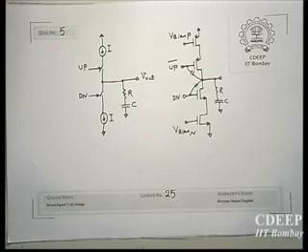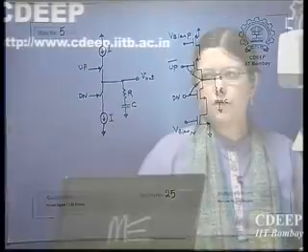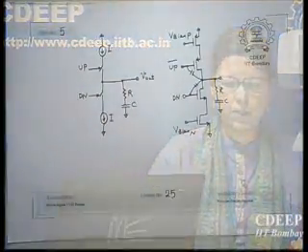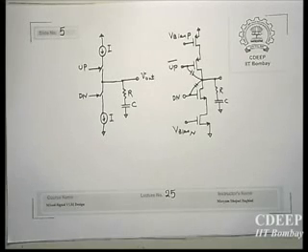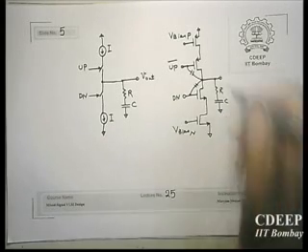Though we would expect this RC will take care of that, the problem is that because now you have an R in series with C, the voltage across C doesn't change instantaneously, but the voltage across R can change instantaneously. Therefore you will see some jump and again it will come back to a steady state. So these spikes are problematic.